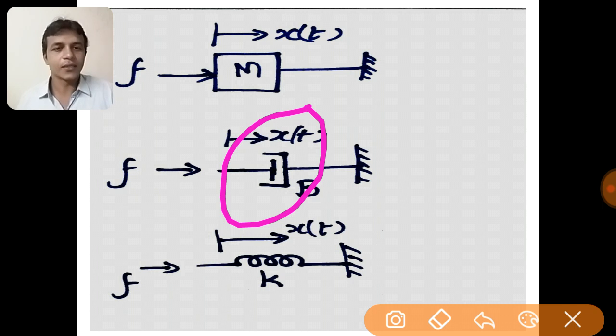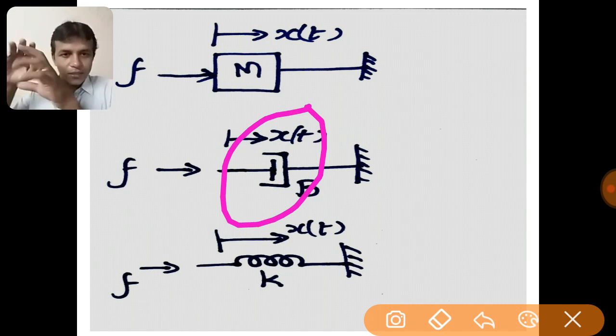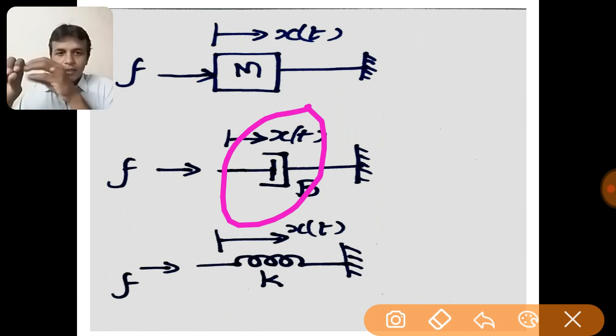So how does it occur? It occurs because of this dashpot. When people open the door, there is a structure inside which is fixed, and inside the structure there is a gap. When the door is opened, the piston in the gap releases, and through the vent the oil, the viscous fluid or dashpot fluid, enters and fills the gap.